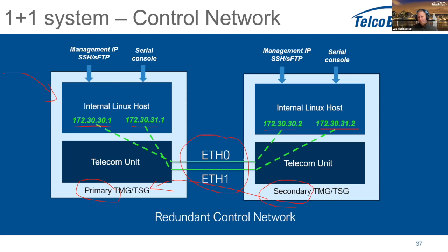Here I show them directly connecting between the two devices, which is the suggested configuration, but it could also go through an Ethernet switch, with Ethernet connections going this way and this way. The only thing is, on the switch you need to configure the VLANs, and the default VLANs are 710 and 711. So it's possible to do something like this as well.